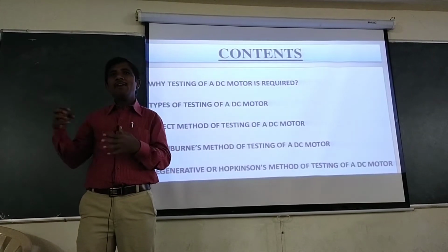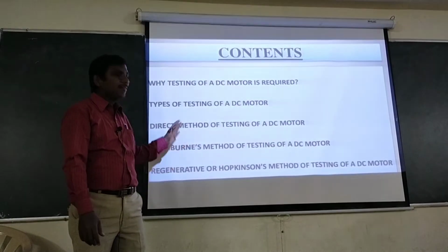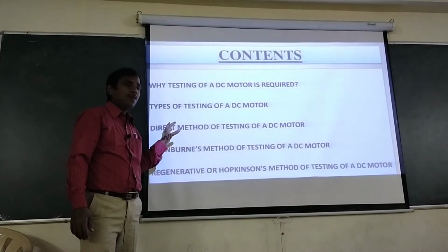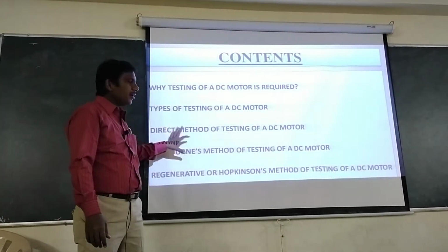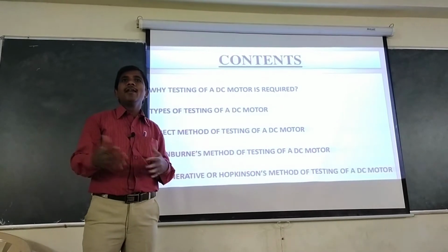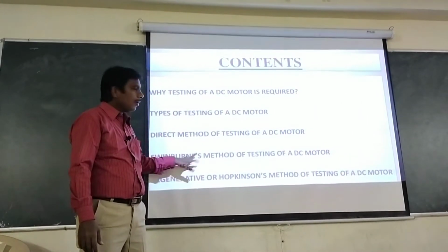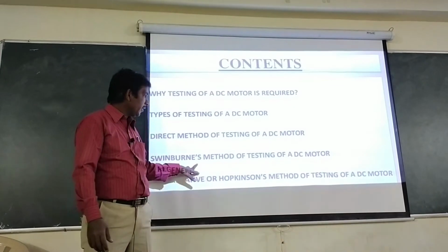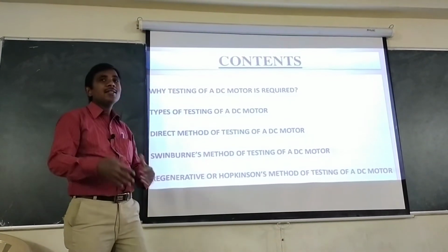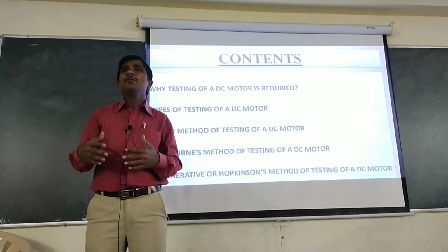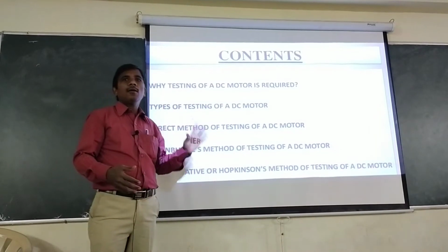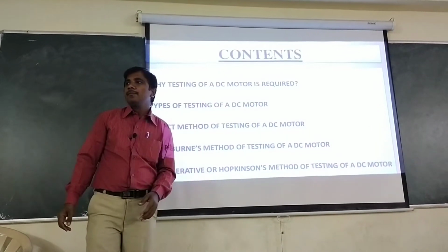Direct test means we directly apply the load and find the efficiency of the motor. Whereas an indirect test is without applying load, where we indirectly measure the losses of the motor. And another one is the regenerative test. The regenerative test is nothing but the Hopkinson test.